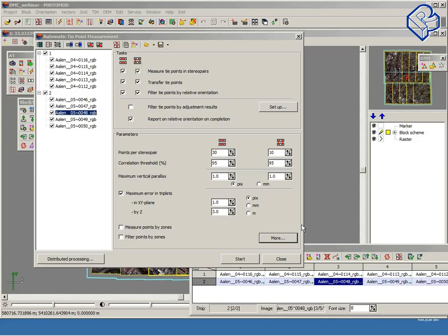So you mean the aerial survey with the GPS IMU system, and how many checkpoints do you need in this case? Well, it's hard to say, but if you measure several points, you can estimate. The main idea: if you have a systematic error of your GPS IMU data, it will be enough to have several points just to see that all vectors are directed in the same direction.